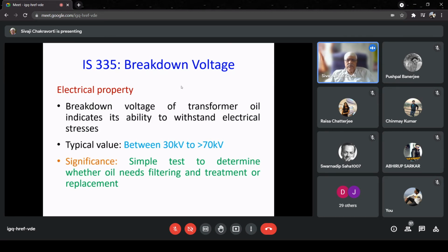So how do we represent it? We represent it as breakdown voltage per unit length. Now, the moment we say breakdown voltage per unit length, its unit does not remain kV. It becomes kV per millimeter, kV per meter, whatever. But the moment it is voltage per unit length, that quantity is not electric potential. Voltage per unit length is electric field intensity. So breakdown strength tells us the maximum electric field intensity that a material can withstand. Every material has a value of maximum field intensity which it can withstand. That's a property of a material irrespective of the sample size.